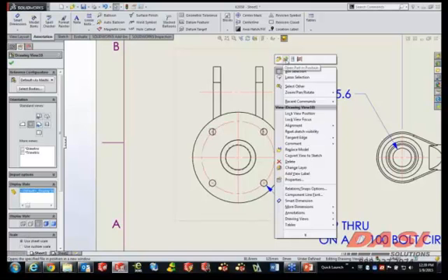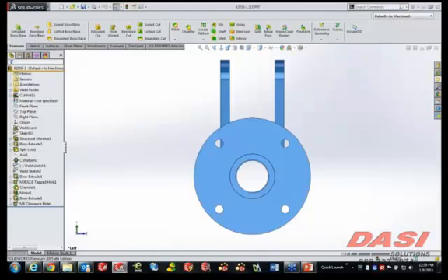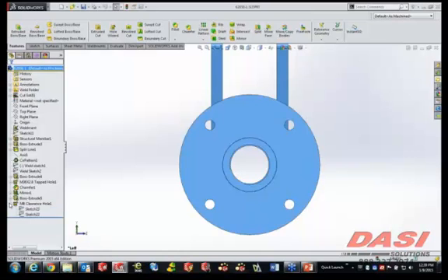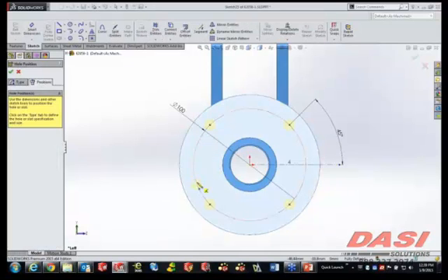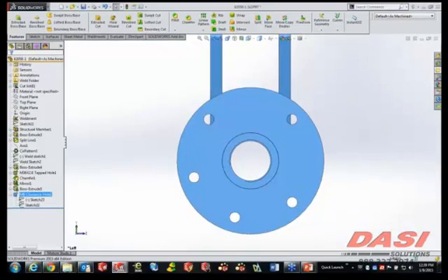Now, regardless of how that part file was saved in 3D, it will open it, and then it will rotate it around into the position of the view that I just interrogated. Now, in order to simulate a problem, we're just going to edit our hole wizard component. And by going to positions, I'm going to add a couple of additional points. But to break something, I'm going to delete an existing point as well. What that'll now leave us with is 5 holes instead of 4, but they're different holes than they were before. At least a couple of them are.